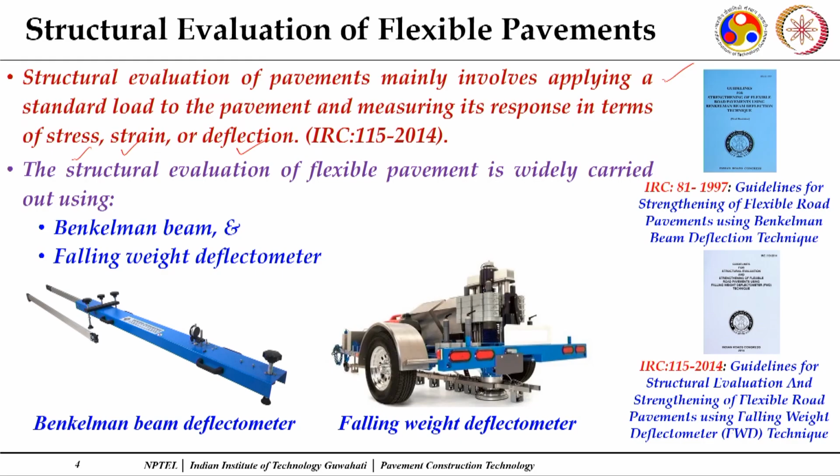Two codal provisions are there. One is IRC 81, the guidelines for strengthening of flexible road pavements using the Benkelman beam deflection technique. The second is IRC 115, the guidelines for structural evaluation and strengthening of flexible road pavements using the falling weight deflectometer technique.